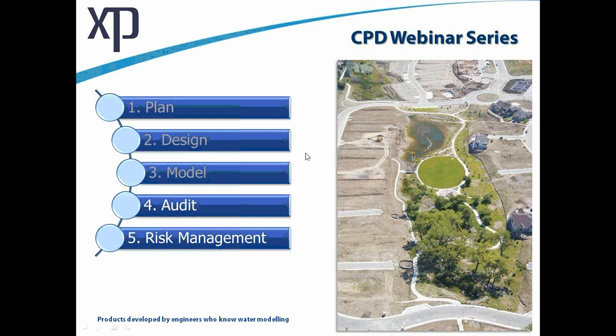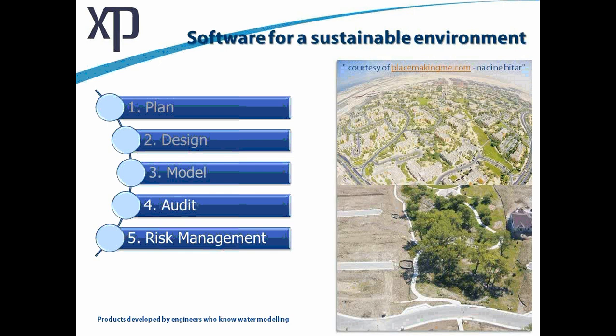Then we've designed a flow conveyance system, and we've then created an integrated model by adding into that system flow controls to limit discharges off-site, and also we've added in a range of structures to complete an integrated model to provide us with multiple benefits and to minimize the cost of construction, because should we be able to infiltrate into the ground, that can save quite a high volume of water storage under the ground, and it's that volume of water storage that costs an extra amount of money.